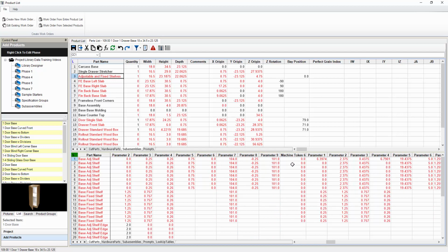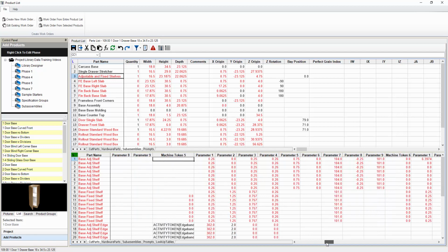They won't show up in your Library Designer, and it's going to really cause a lot of problems for you. And when it goes and rebuilds the updated data, you're going to potentially lose a lot of the spreadsheet data. So you never ever want to have a blank column unless that is really the last token.